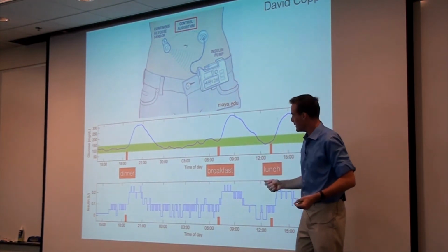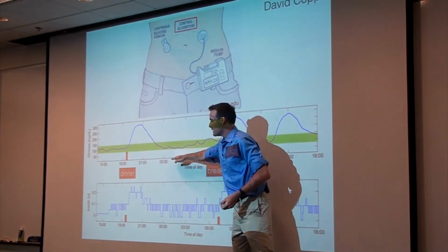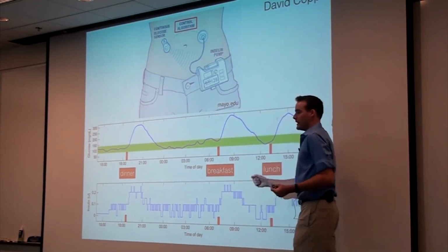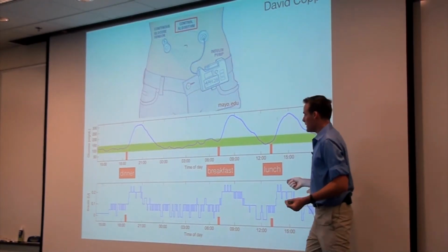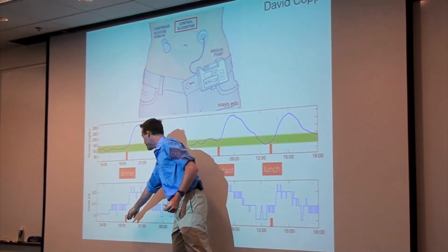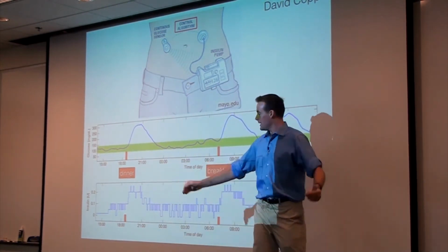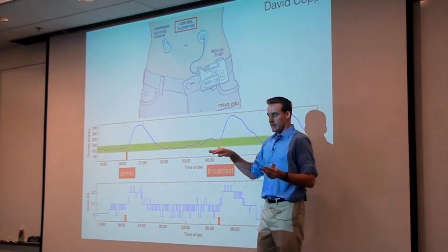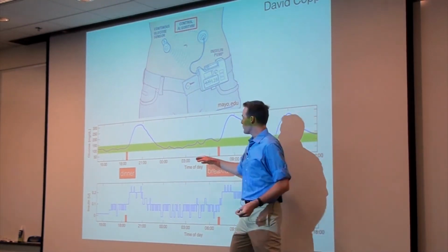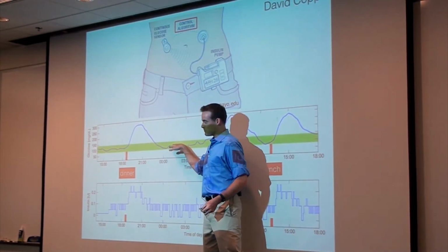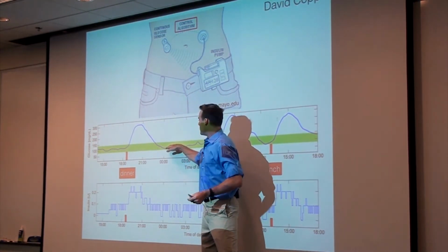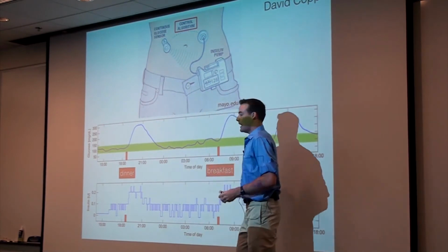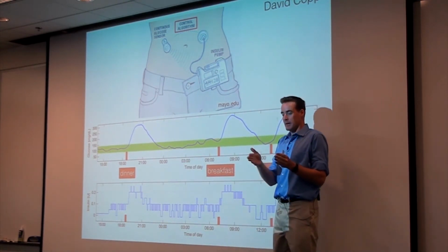There is a hard constraint. You must not drive the blood glucose level down too low, or the patient will go into a diabetic coma. So David has a different kind of controller, and every 5 minutes it computes 45 minutes into the future. It says, what is the best insulin trajectory that I should assign for the next 45 minutes in order to bring the blood glucose level down as fast as possible, subject to the constraint that it does not bring it too low, that it does not bring it into the coma level. And then it executes that plan for the next 5 minutes.